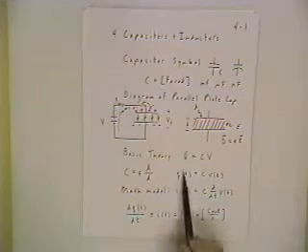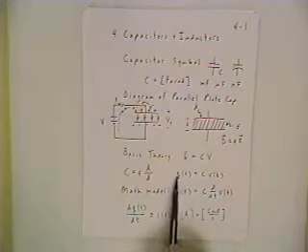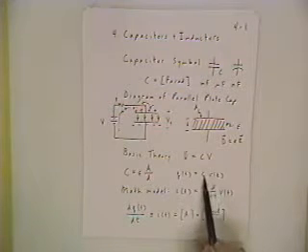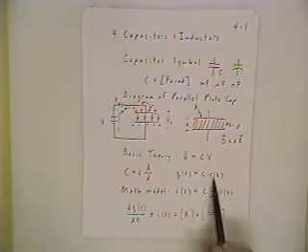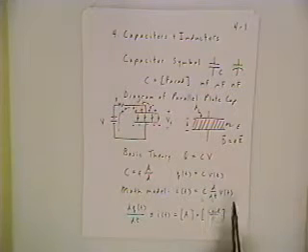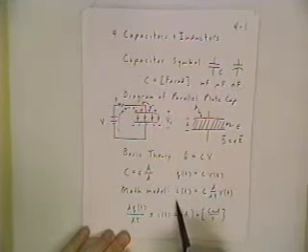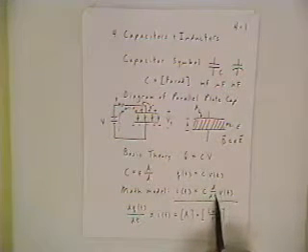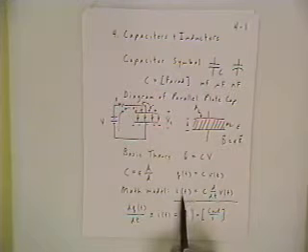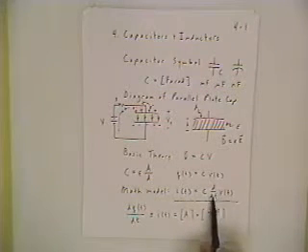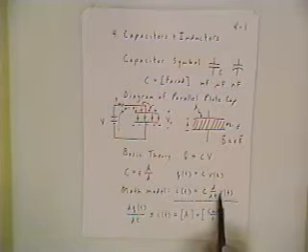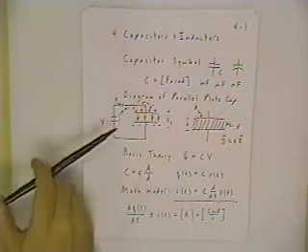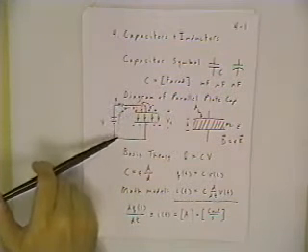And you can see where that simplifies the left-hand side of this equation. Once you do the derivative, dq/dt, replace that with current I. On the right-hand side, C is a constant, and you replace the voltage term with a dV/dt term. So what this mathematical model is telling us is that as long as the voltage across the capacitor is changing, we're going to get a current through that capacitor. But once we have a capacitor fully charged and the voltage is a constant, then the current in the capacitor goes down to zero. And that matches up intuitively with what we have up here with the charging capacitor.